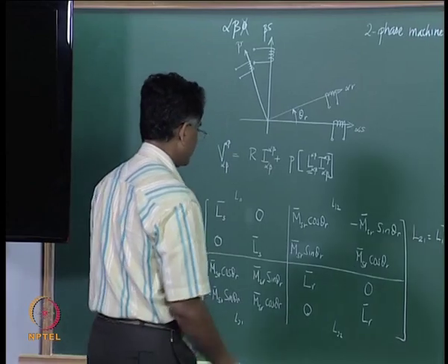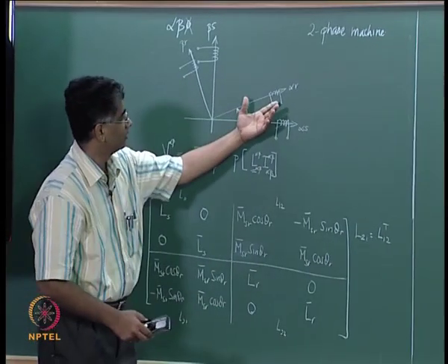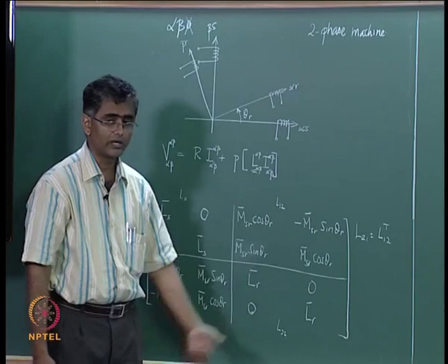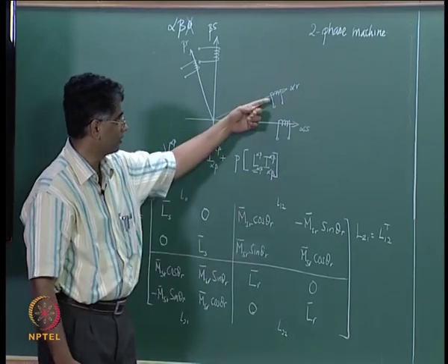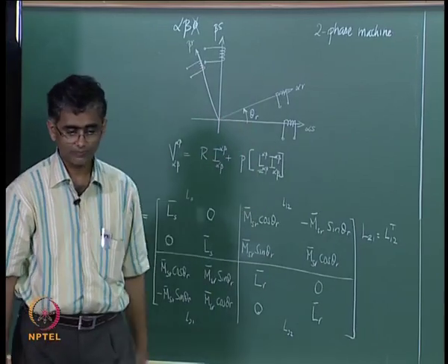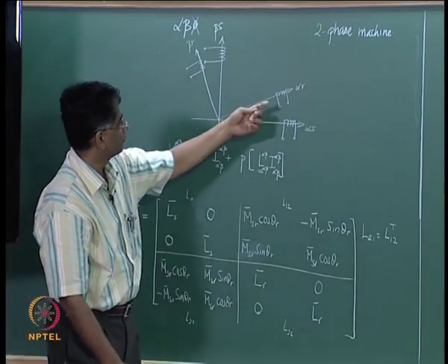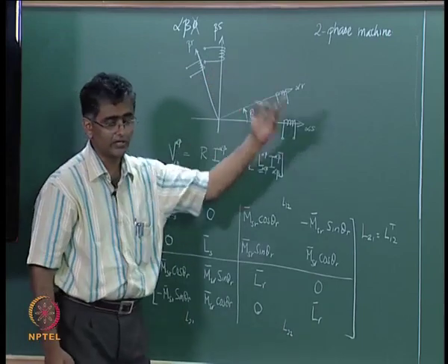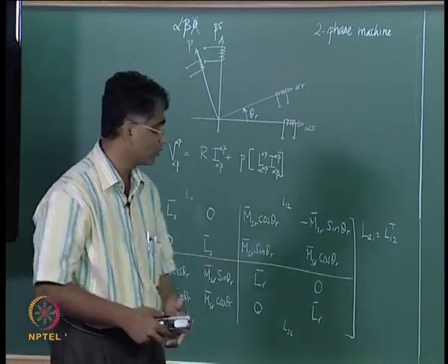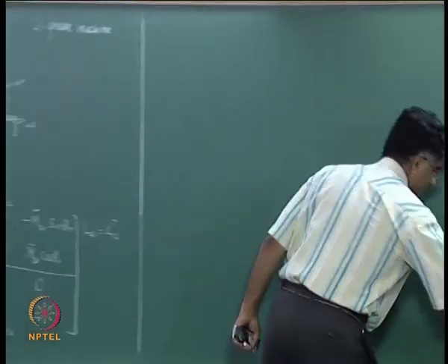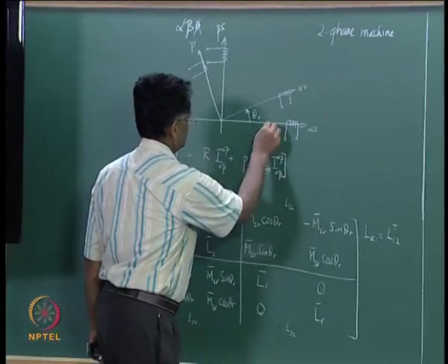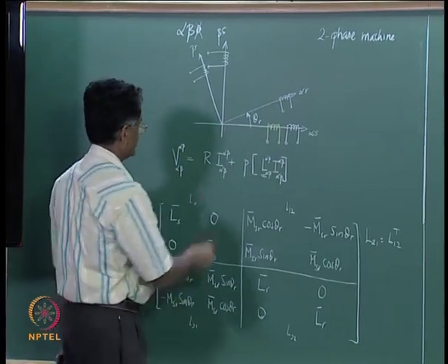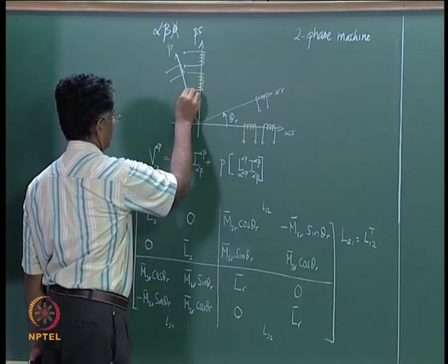And in order to get rid of that, we said that one can transform the rotor to a stationary axis, having observed that the rotor angle arises or occurs in this description because the rotor is moving with respect to stator, and looking at the MMF produced by the rotor alpha r axis and the beta r axis at a given angle phi, yesterday we found that the same MMF could have been developed by 2 coils that are placed here, one on the alpha s axis along the same axis as alpha s, another along the beta s axis.